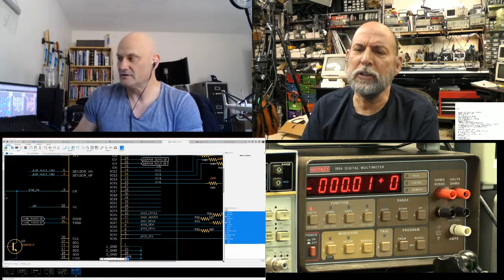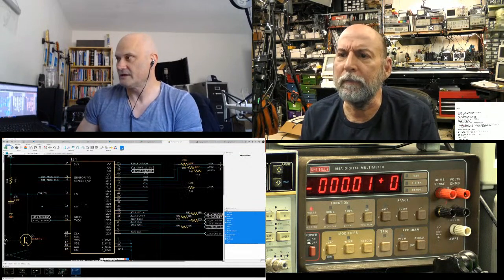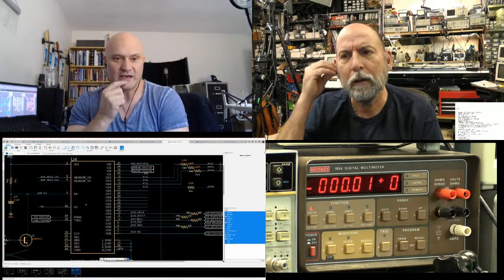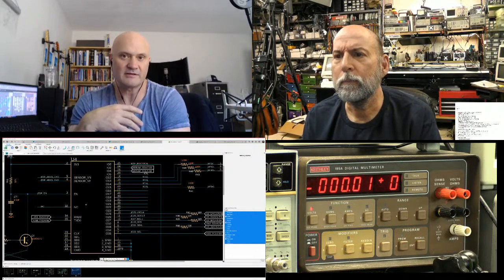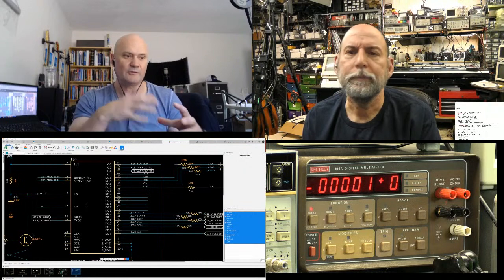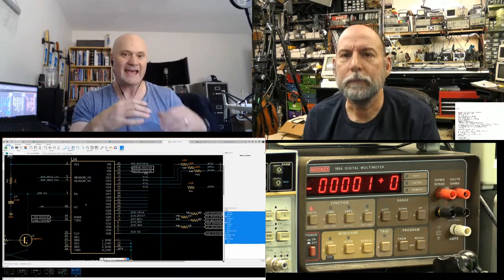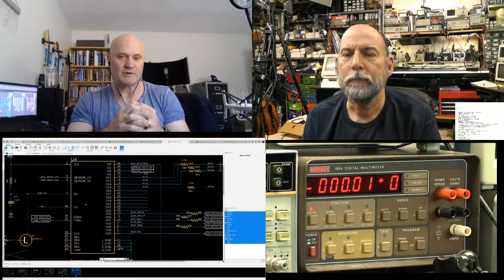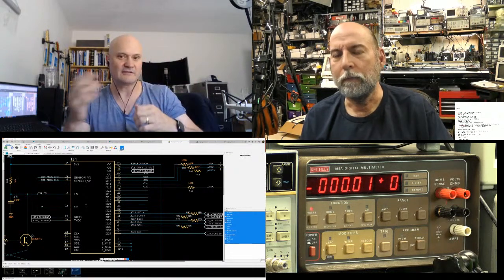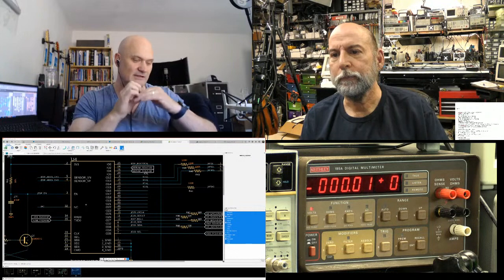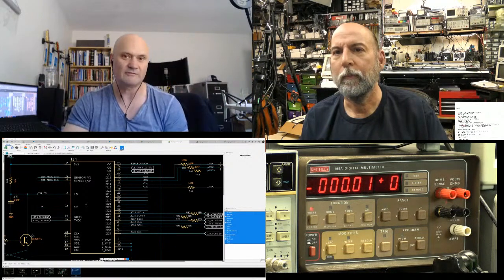So does it support ULPs like Eagle used to? Yes. ULPs and SCRs, you can automate it, but Fusion has its own Python scripting engine. So eventually the whole thing will be accessible at a higher level through the Fusion Python API. And so you'll be able to automate not just the ECAD part, but maybe the entire workflow.